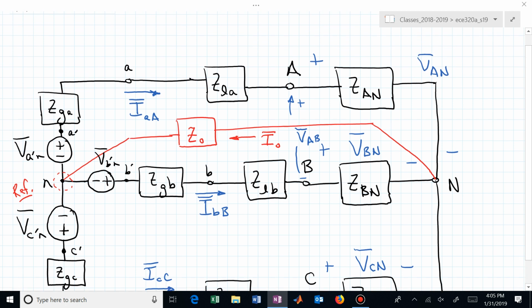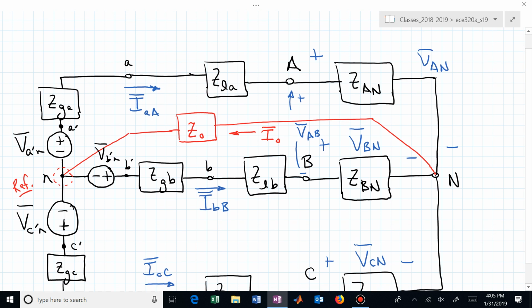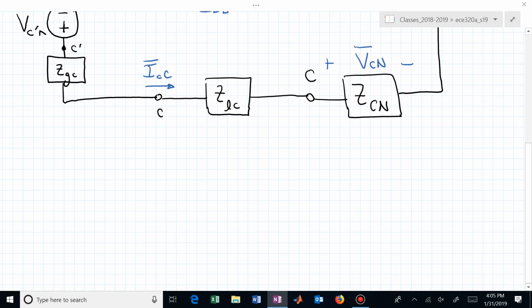And from this diagram, what I want to do is compute the A phase complex power. So let's now say we want the A phase, and that's actually not yet precise enough. If I said the A-phase complex power, you're going to say, of what? It needs to be of the source, or of the load, or the transmission line.